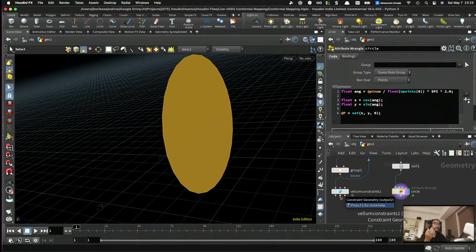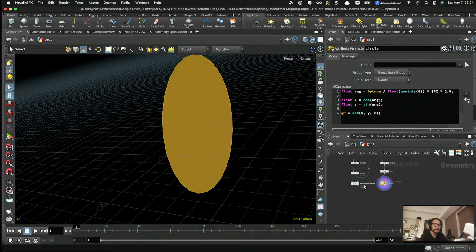So I want to limit the Z coordinate of the simulation to be equal to 0. In order to do that, you need to go inside a subsolver to modify the point positions forcefully. So for that reason, I'm also going to pin the boundary inside a subsolver.